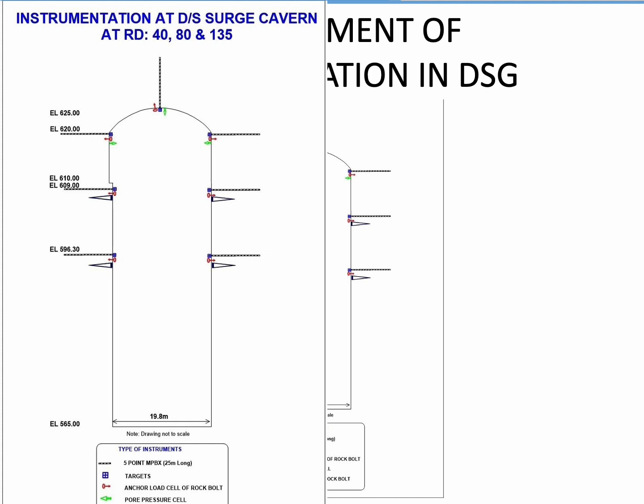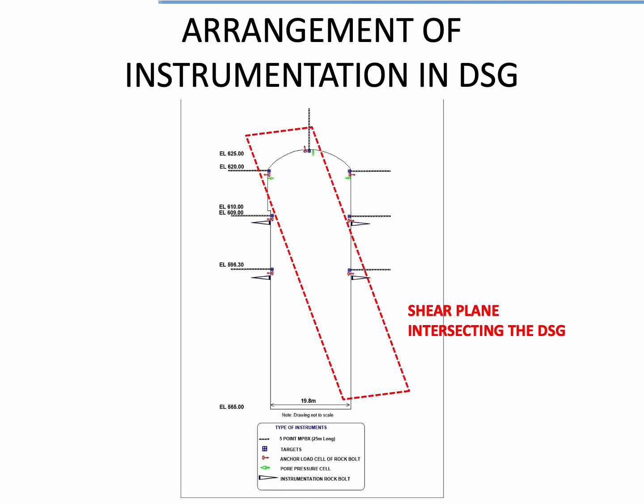There are multiple extensometers, 3-point MPBX, surface targets, anchor load cells of rock bolts, pore pressure cells at such locations and elevations are provided.